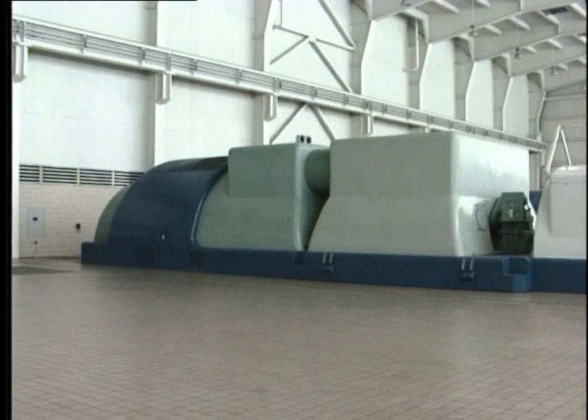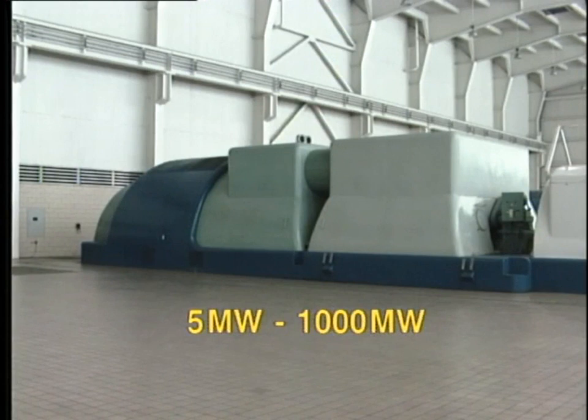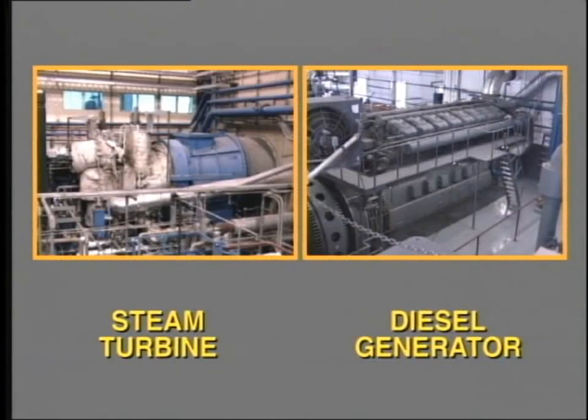The steam turbine is certainly one of the most popular prime movers, especially for driving large power generators. The size of steam turbines built and installed runs all the way from about 5 megawatts up to 1,000 megawatts or more. So what is it that makes the steam turbine the preferred prime mover in comparison with, say, the diesel engine? Well, there are quite a number of advantages, the main factor being that of physical size. For example, a 30 megawatt steam turbine is probably smaller than a 5 megawatt diesel.